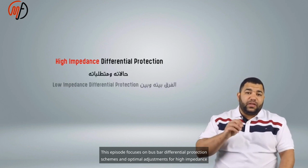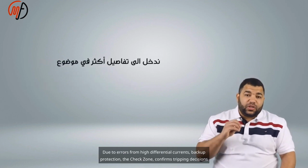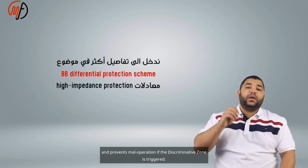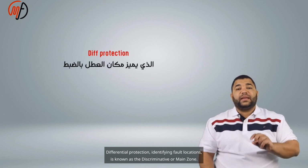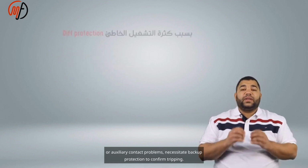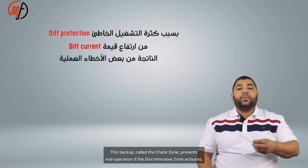This episode focuses on bus bar differential protection schemes and optimal adjustments for high impedance protection. Differential protection identifying fault locations is known as the discriminative or main zone. Frequent operational errors due to high differential current from issues like open circuits in CT circuits or auxiliary contact problems necessitate backup protection to confirm tripping. This backup, called the check zone, prevents maloperation if the discriminative zone activates.